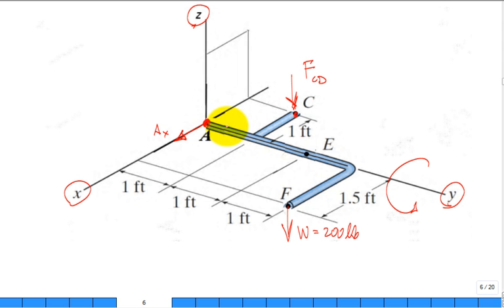Likewise, you can either put it this way, AY, or you could put it this way, AY. Either one, but you've got to pick one or the other. Let's put it at the base going out to the head, AY. And then this one is AZ. So there's three potentially non-zero unique components of the reaction at A due to that ball and socket.